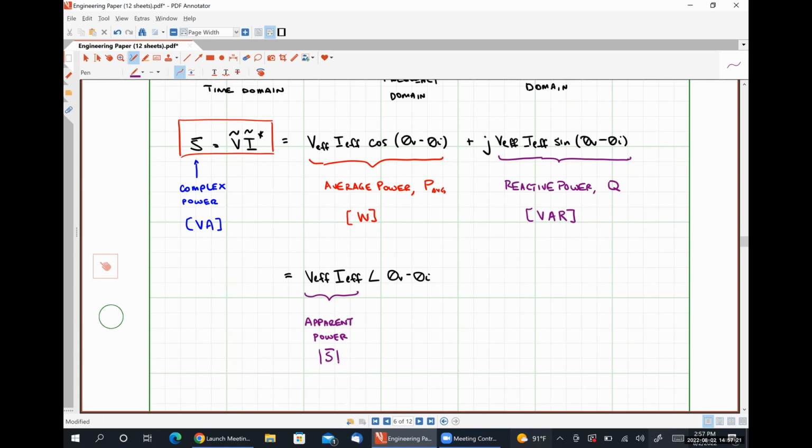So if you've ever tried to buy a generator or an uninterruptible power supply for your computer or home appliance or anything like that, they are typically rated for some amount of average power, so like 1800 watts, and some amount of apparent power like 2100 volt amperes. Okay. As a power engineer, you use the quantity apparent power a lot to make sure that you're sizing your conductors properly, to make sure that you're not going to start fires and things like that.